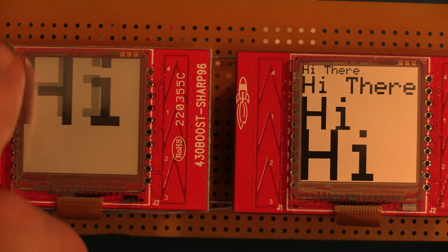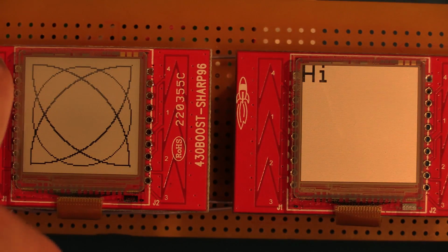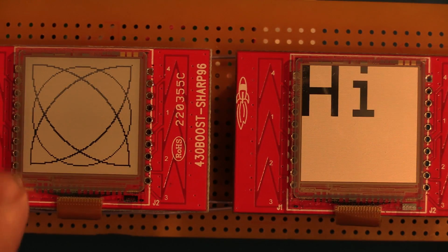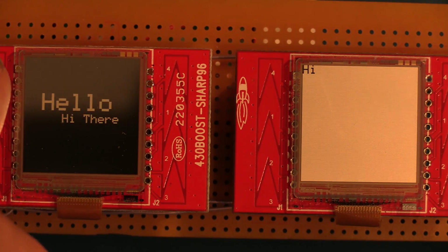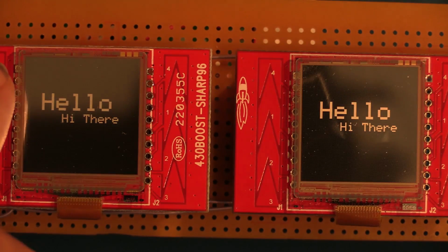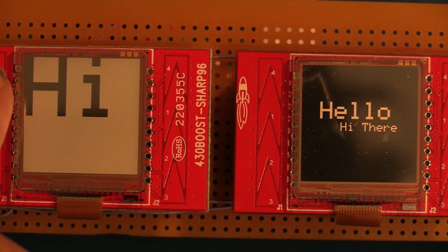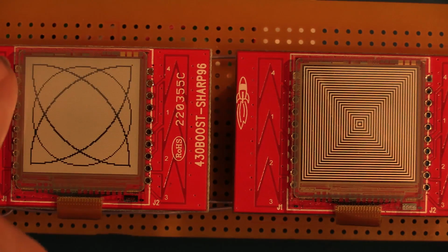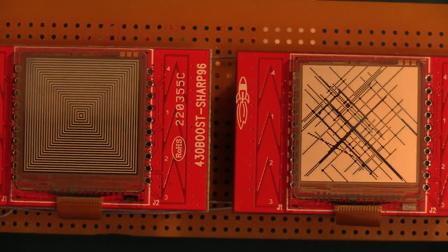But when you're doing the addressing as you come down here, normally you would think you would have 00, 01, 02, 03, 4, 5, 6 coming down here. But it isn't. You actually have to output 00 for the very top line, then 80 for the first line, and then you output 40 for the second line and C0 for the third line. So the bits are basically swapped for the addressing. Don't ask me why they did that, but that's the way it works.